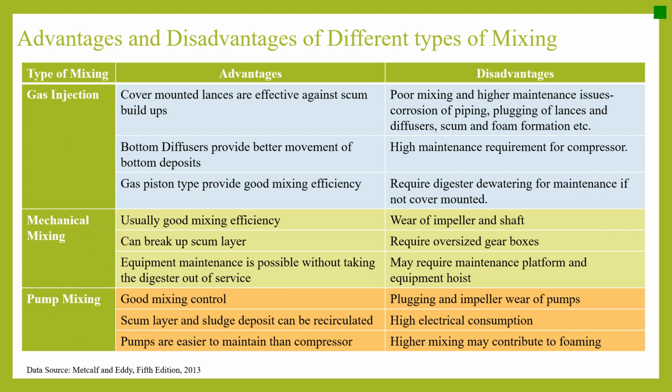Mechanical mixing: usually good mixing efficiency, can break up the scum layer, and equipment maintenance is possible without taking the digester out of service. Disadvantages: wear of the impeller and shaft, requires oversized gearboxes, and may require a maintenance platform and equipment hoist.